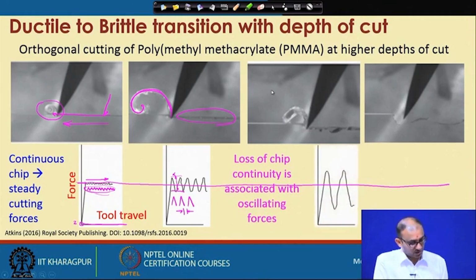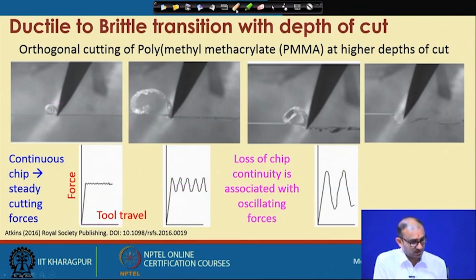Now, this one is the third one. In this case, on the machined part there is a large amount of deformation, fractures, or some type of unwanted features on the surface. The chip is also different now. It is coming out in a very awkward form, and you are not able to identify the particular shape of these chips.